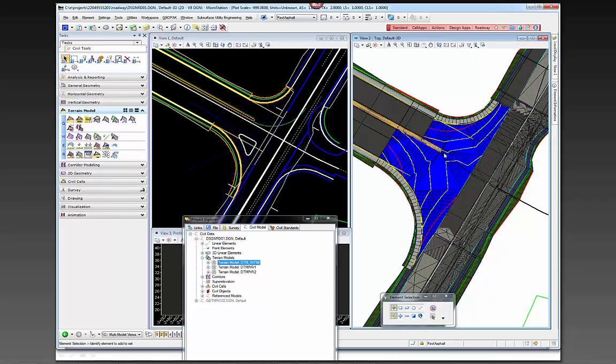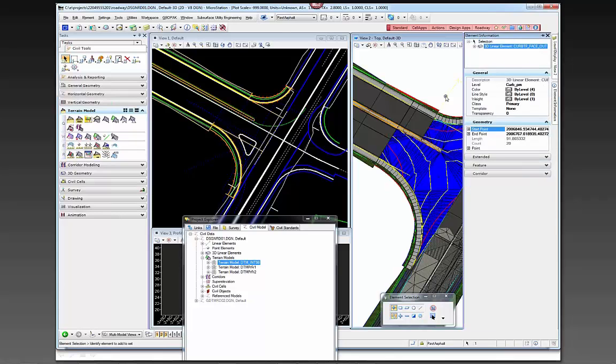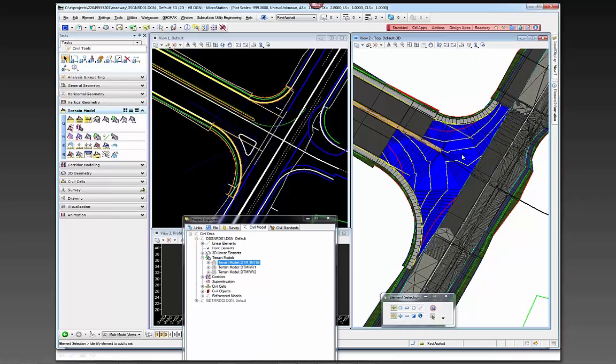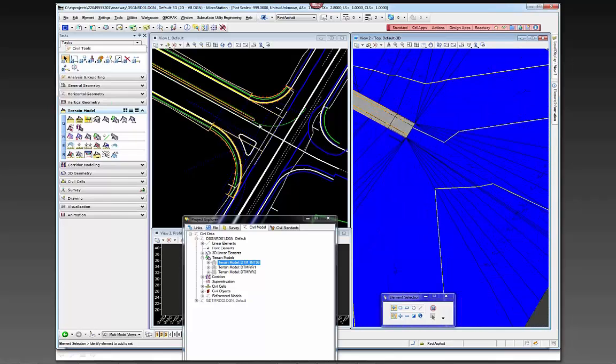You can go in and if you wanted to, it looks like it's breaking across here. It's coming to a low point over here, and then this is coming to a low point over here, or possibly this is the high point and it's going around that corner. Yeah, that would be that situation. Looks like it's breaking here and coming to a low point somewhere around in here. So if you needed to regrade this a little bit, you could go into the profiles of these radius lines and actually rebuild it. So let me go ahead and add that traffic separator nose on here again,